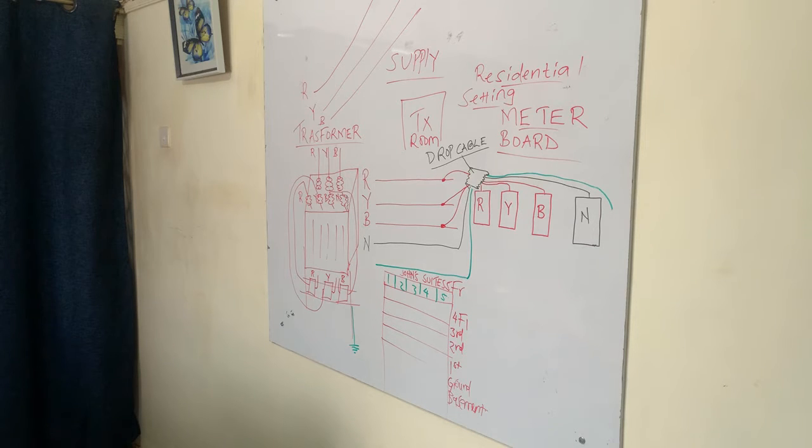So we must ensure that we do good balancing, whereby we are able to balance the distribution properly and have our phases well distributed to the loads. Because if you don't do that, then you are inviting a problem whereby that transformer will have an issue, and it will also mean that you will have problems with the national power distribution.